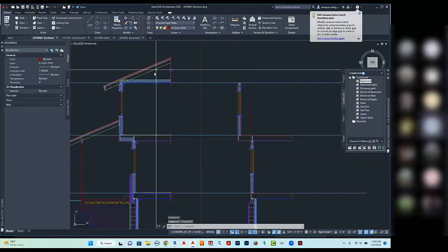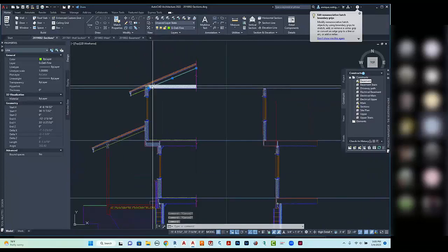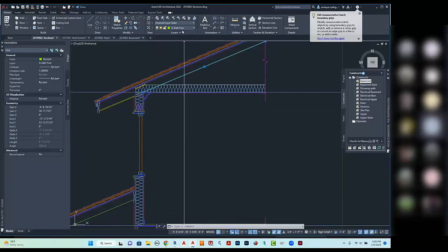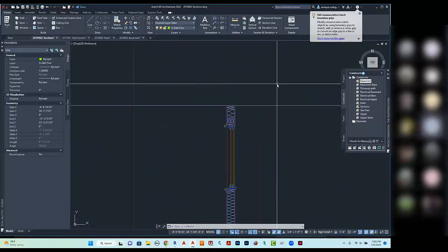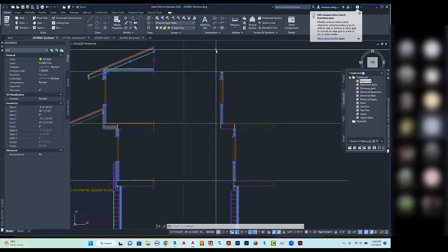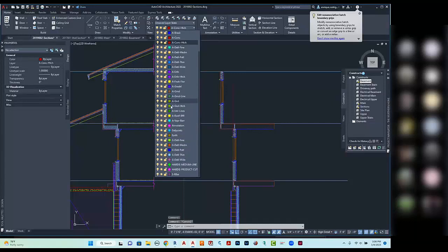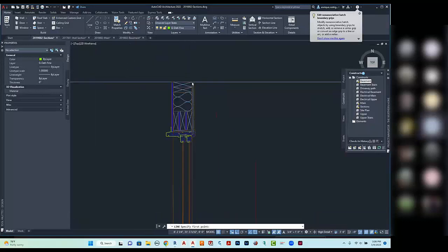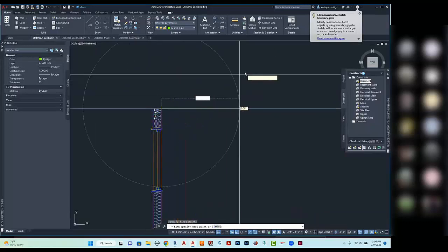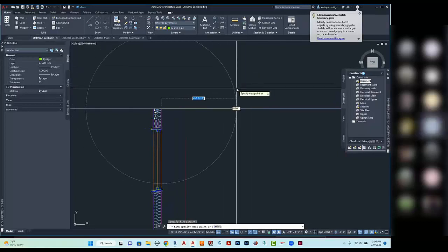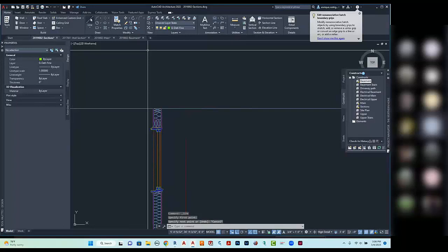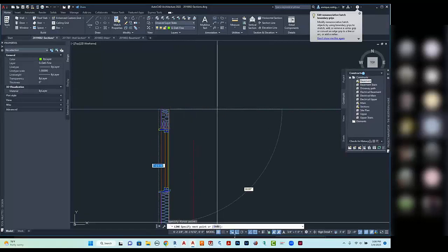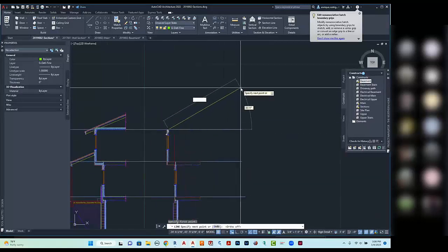I'm going to go ahead and just use line work for this, although I could use a rafter and then edit it. All right, so I checked what the line is. It's G detail fine. Again, we're not cutting it in section. So I'm going to set that as the current layer. Go down to G detail fine. And I'm going to draw a line from this point. Turn off my ortho. Stretch it out to there.